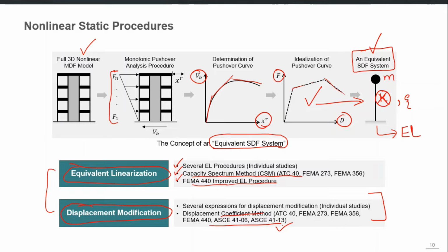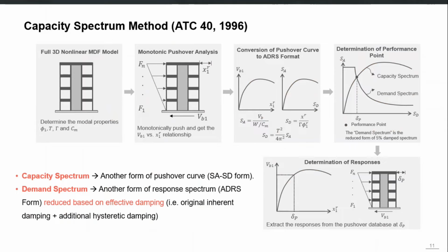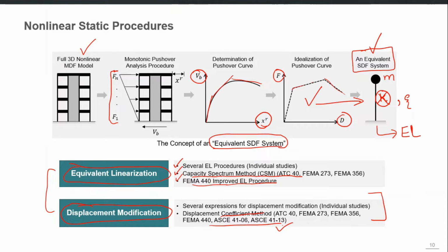So although we will not go into details of these methods, our target is to discuss the multi-mode pushover. But I want to just quickly show you in just one slide each of these methods. But before that, there is a third method also I want to highlight. So if this is the first approach, this is the second approach, there can be a third approach also, and that is that once we develop the nonlinear equivalent single degree of freedom system for our multiple degree model, we can simply perform the nonlinear time history analysis of that single degree of freedom system.